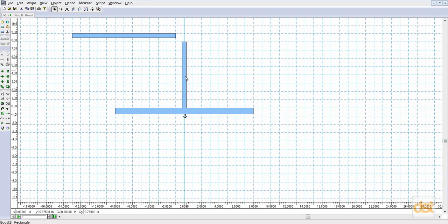And then for this vertical post right here, we could also add an anchor if we wanted to, but we're not able to determine reaction loads when using meters at anchors. So if you desire to determine the reaction force at the base of this post, then what you'd want to do is use a rigid joint and rigidly join it either to the background or to this base part right here. The last thing we'll do is pin the beam to the top of the post.